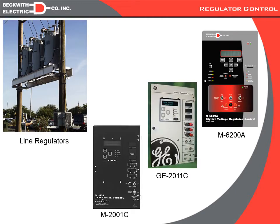So the M-6200A is the latest of our single-phase regulator control products, starting with the original 2001 and now up to the 2001D. But the 6200A was engineered specifically and only for single-phase regulators. So unlike the 2001 line, the 6200A should not be used for load tap changer controls, LTCs, as we don't have adapter kits for each of the different LTCs. And also it does not have a second CT that would be required for paralleling of transformers.